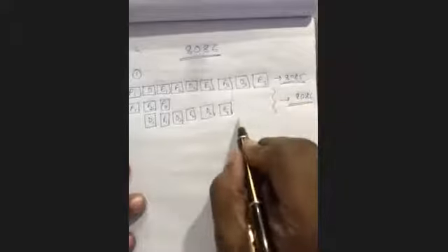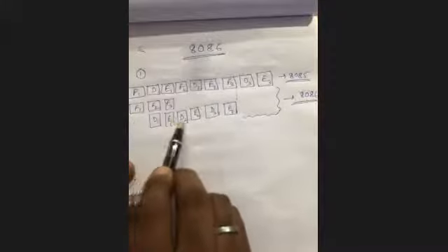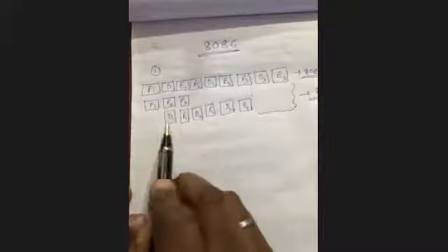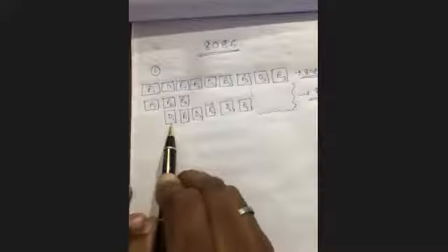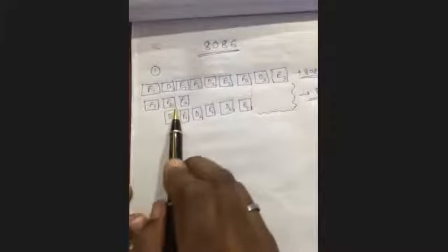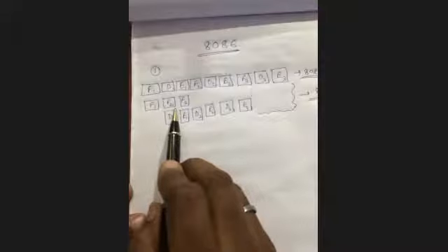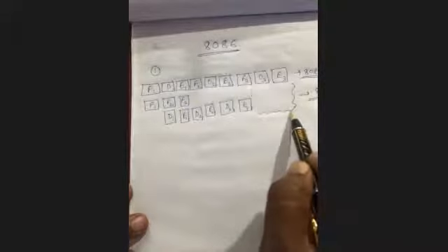So this block of time will be saved for 3 instructions. Am I right? Yes, sir. It means fetching and decoding-execution are done in parallel. When the instruction 2 is being fetched, at that particular time, the decoding of instruction 1 is done simultaneously. So this time is not required in 8086, the same time which is required in 8085.